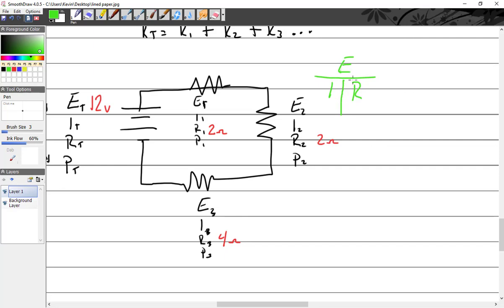And that is to say that Ohm's law, E equals I times R. And I can look at that by just covering up any one letter of this. If I cover up the E, I have I times R. If I want to know I, what's the formula? It's E divided by R, so it's E over R. And what is the formula for R? E divided by I. All right, so that's easy enough, right?